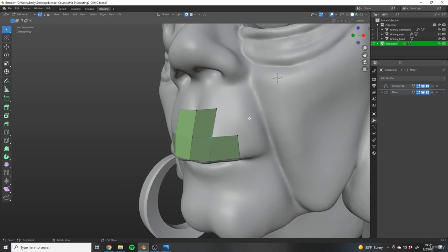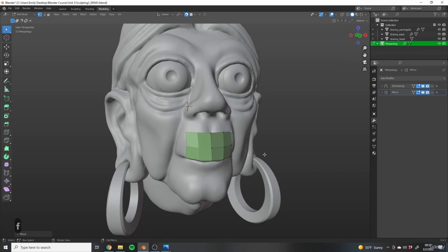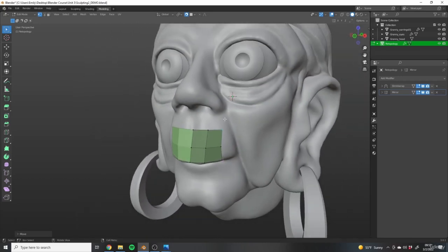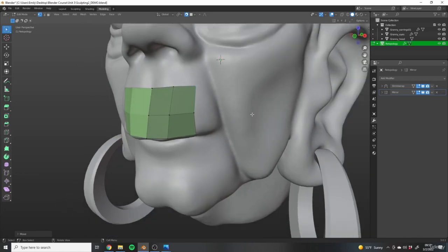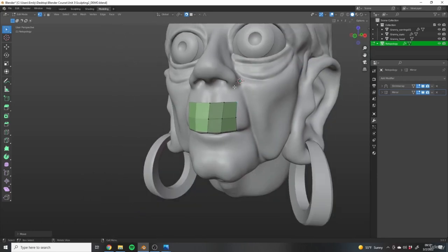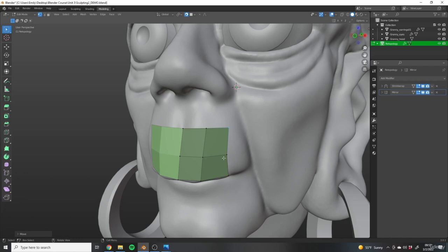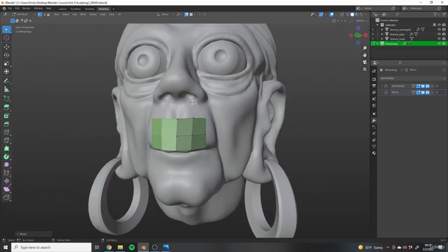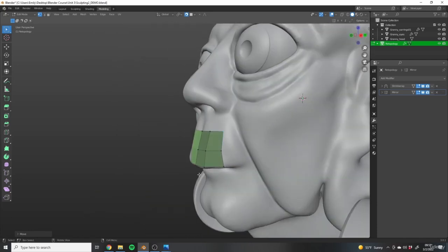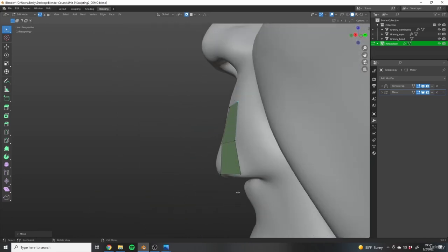But with the F2 add-on, now when we press F, it creates a perfect quad. And it draws that point out here. So this is just a sort of workflow speed up that instead of having to extrude and merge these points, we can just quickly add a new point here. And keeping these faces all quadrilateral is extremely important for having a good topology when you're retopologizing something, especially for animation.